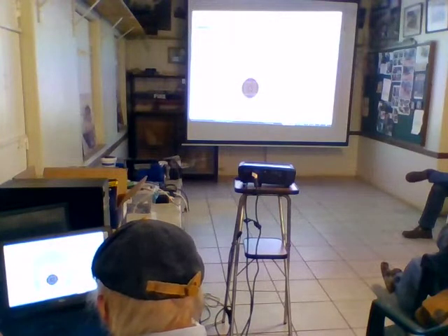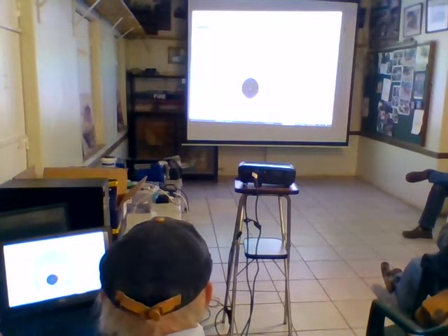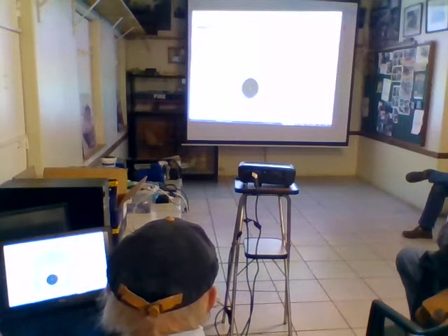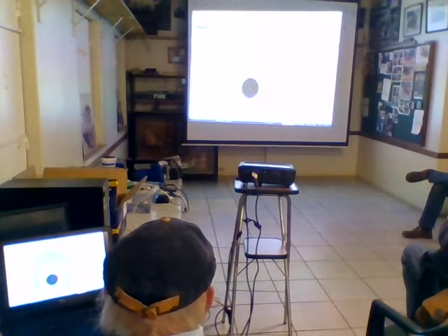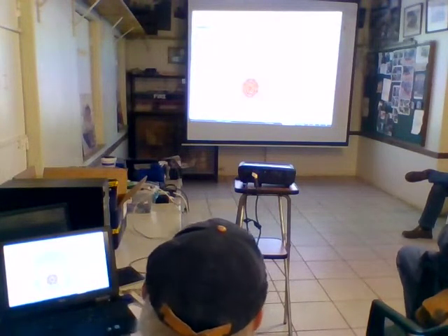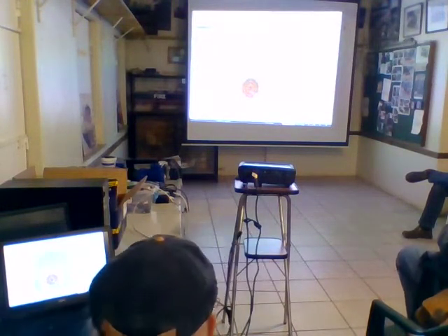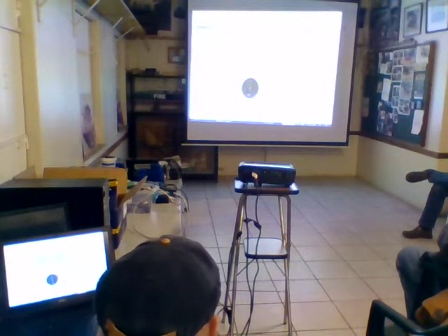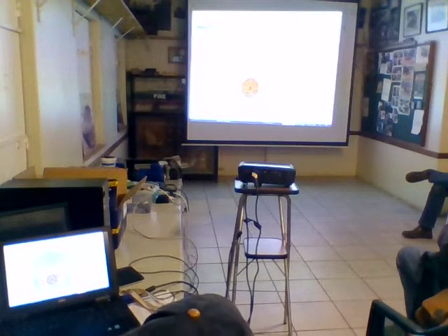So the table is tilted by this motor on the left-hand side, and this table is turned by a motor that sits underneath here. There's a flat motor that turns this table here. So that gives you the 4th axis, this being this axis, and the 5th axis being this rotary table. So it can be a 5-axis machine in the end.